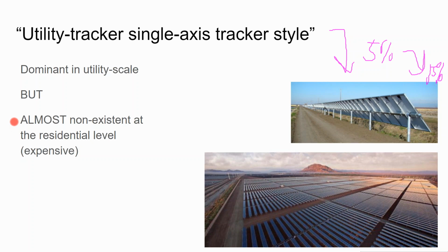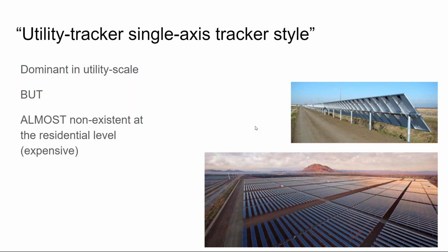But it's almost non-existent at the residential level. Well, why is that? Well, a lot of solar installers will tell you, oh, whatever money you'll spend on tracking, just use it to buy more solar panels. Well, okay. But if I buy more solar panels, add another panel onto this, I have to add a whole new foundation onto it. I'm not just buying the panel, I'm buying the racking and the charge controller capacity and the labor involved and all that. No, the reason why we don't see single axis tracking for residential ground mounts is because there's no